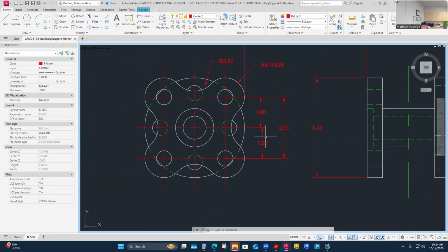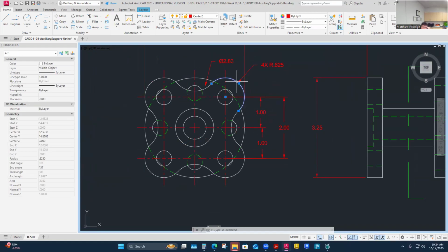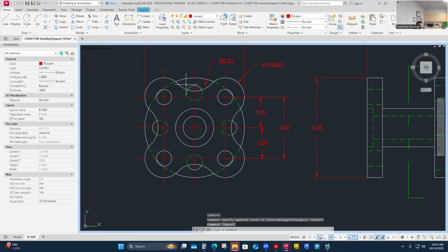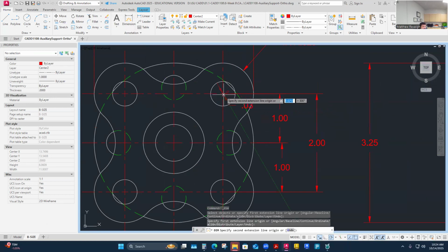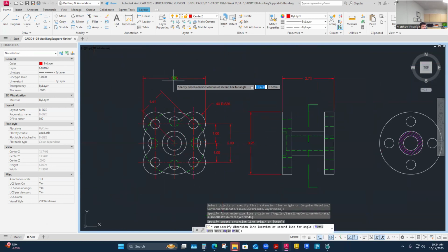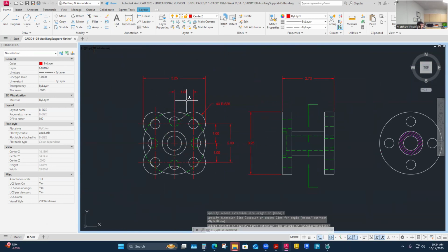So what I've done is located the center of this. It's 1 inch off of this center line here. And really, that's only in one direction. That's in the Y direction. So it needs to be located in the X direction as well. Of course, this dimension I would delete because it's with that other. It makes you have to put those dimensions across this other way as well. For sure, this one, right? This one has to be located 1 inch from center.